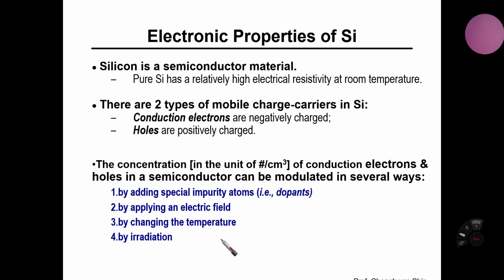Conduction electrons are the electrons that can contribute to flowing current. The electrons themselves indicate the 14 electrons in a silicon atom. But we're going to use the four outermost electrons to flow currents because they are the farthest from the center of the silicon atom, so they are loosely bound to the positively charged particle within a silicon atom. The four outermost electrons will be used, and the electron is negatively charged.